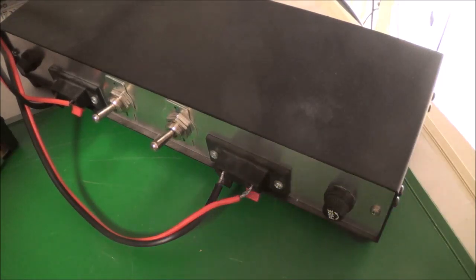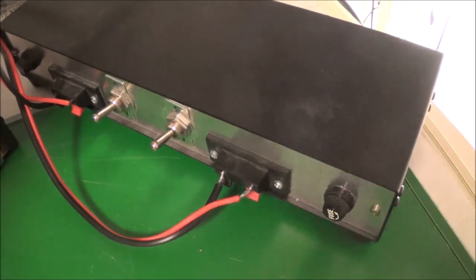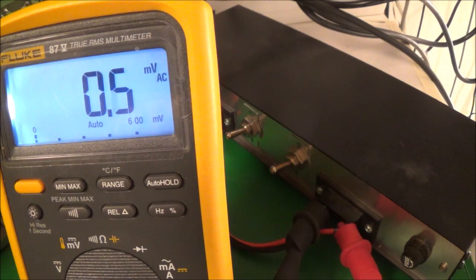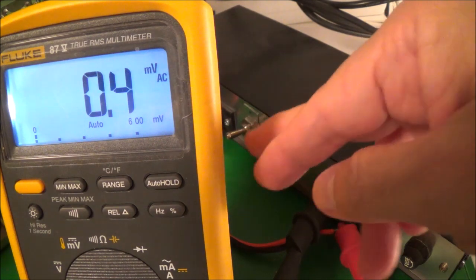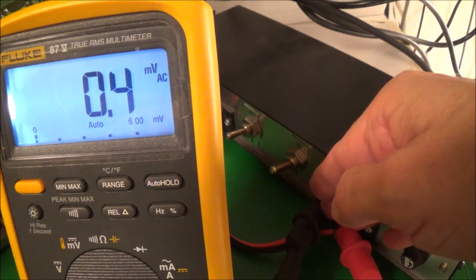Okay, what about the output now? Well, the way I do it is I turn my function generator really down, really low, and I turn the volume control on the receiver and amplifier all the way up. So my next step, before I forget, I just had the unit turn on and shut it off now again. I hook up an AC voltmeter across the dummy load.